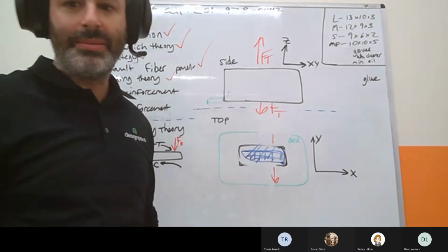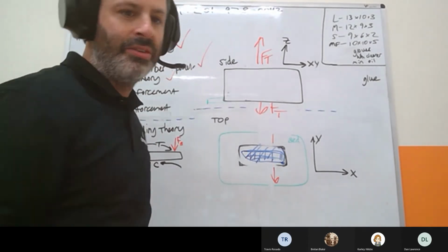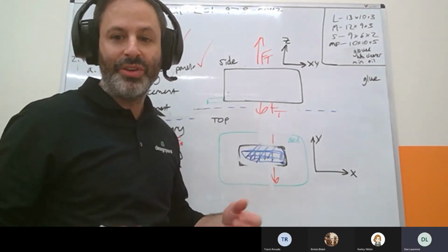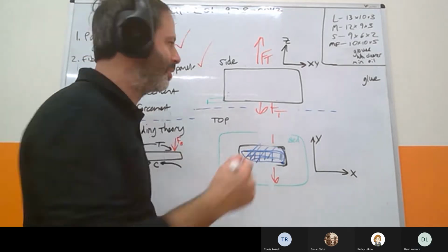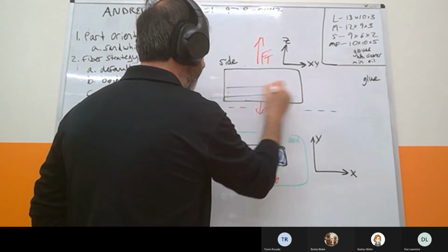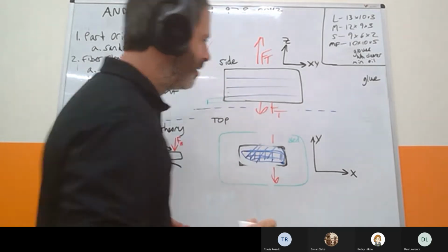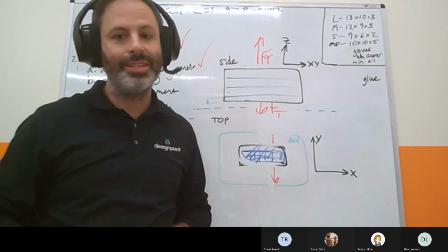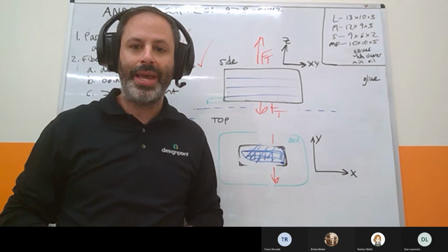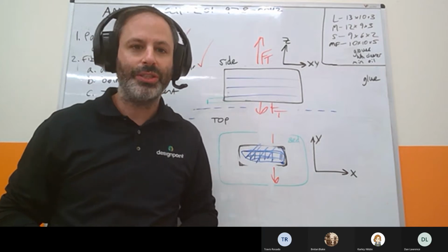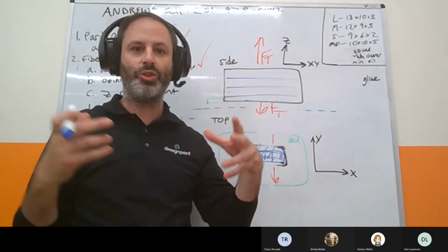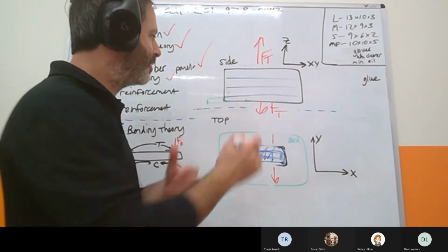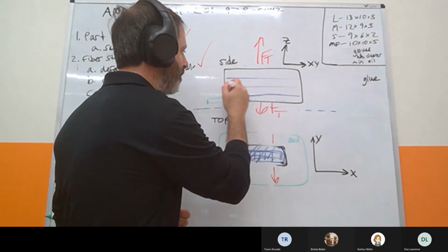So what fiber striping means is instead of adding fiber to every layer, you're going to add it to every third layer, every fifth layer, every second layer. So the fiber would be more spread out. And you can do the striping with concentric fiber, or you can do it with isotropic fiber. I think it just depends what you're trying to accomplish. You have to look at the loading condition. Are you trying to be stronger in Z? Or are you trying to be stronger potentially in X, Y? And then you would decide the actual characteristics of each one of these layers.